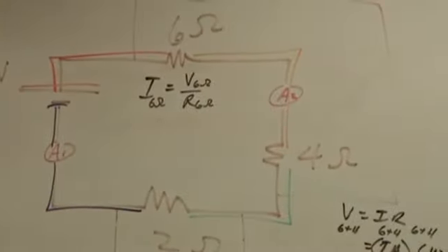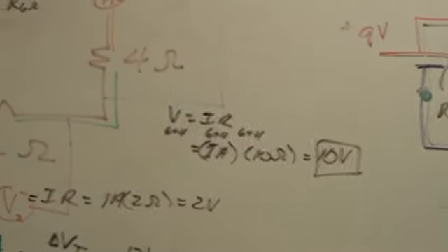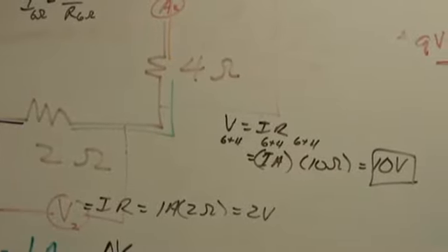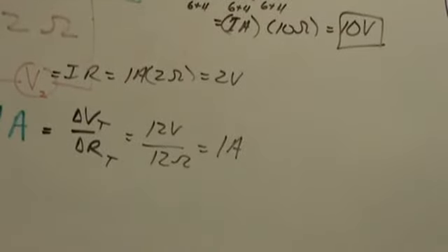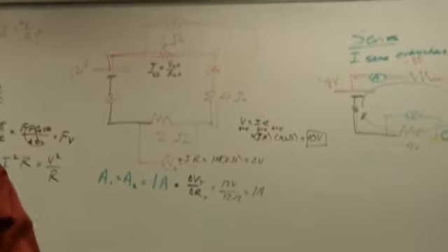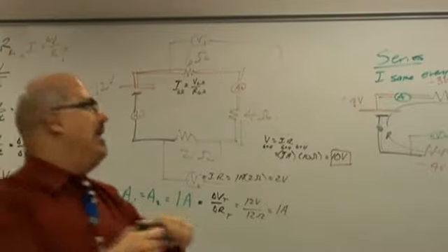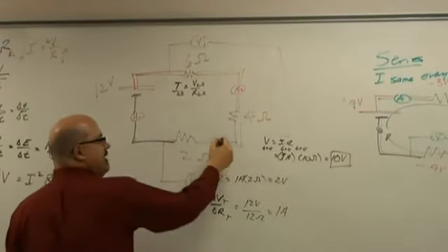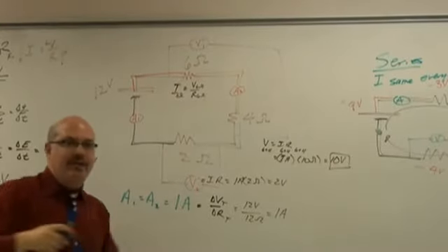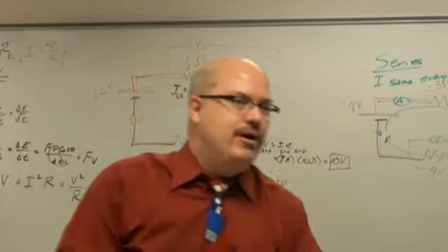When we hook up a voltmeter, we assume no current flows through it. Okay, good point. Everybody, whenever we hook up a voltmeter, we assume our voltmeter has no current going through it. Now that means that our voltmeter, in theory, has how much resistance? Infinite. A whole lot, right? We assume approaching infinity. None of the current gets bled off here. So that means a voltmeter has an infinite amount of resistance. Not really, but yes. Infinite.